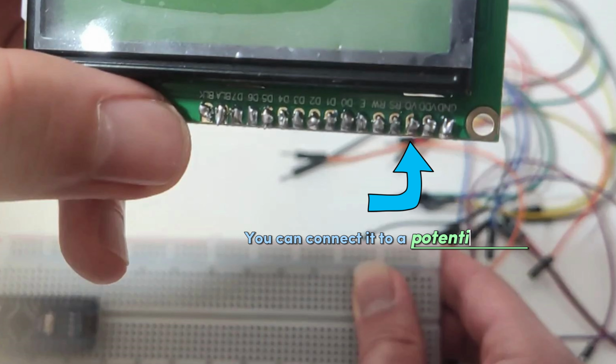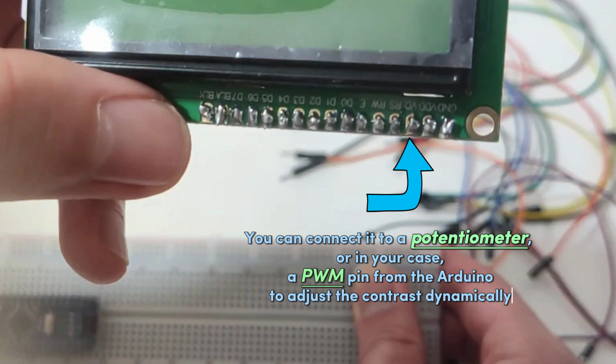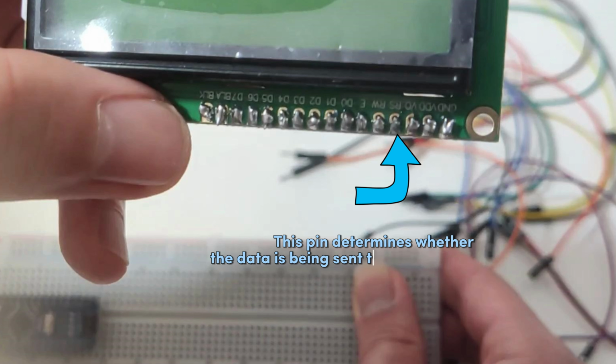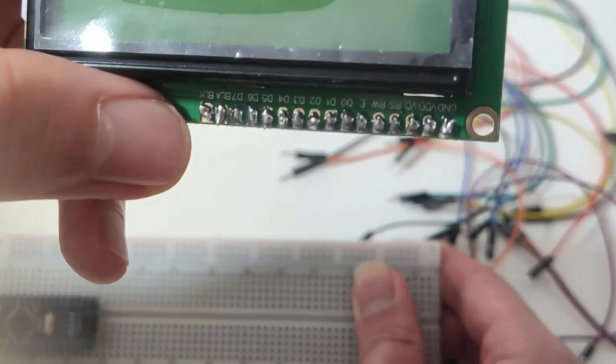Our next pin is VO. This pin controls the contrast of the LCD. You can connect it to a potentiometer, or in your case, a PWM pin from the Arduino to adjust the contrast dynamically. The next pin is RS, or Register Select. This pin determines whether the data is being sent to the command register or the data register.